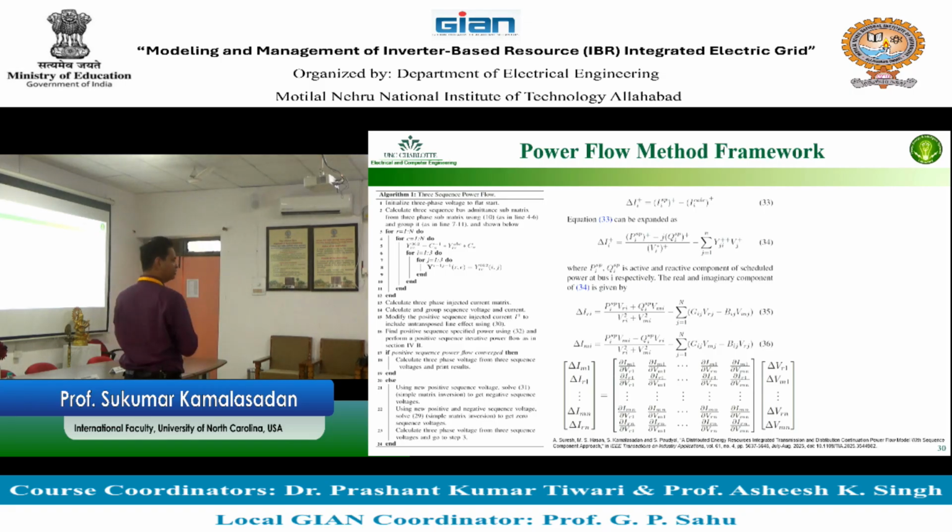Okay, the Y bus is ready, right? Once the Y bus is ready, can you run the power flow with one algorithm? Yes, you can run the power flow now with one algorithm. You have already seen this algorithm before. What is that algorithm? That is the current injection algorithm that we run for the distribution network. The same current injection algorithm, you can run it for the transmission system.